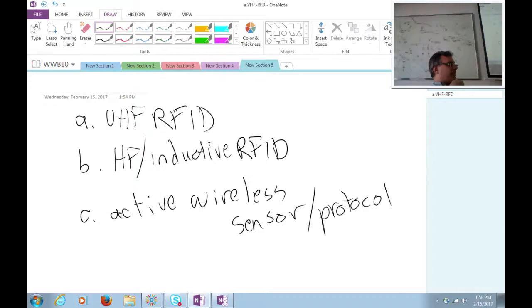I think so too, yeah. In fact, there are casino chip counting technologies based on this. You need to get through a table, which hopefully is not metal. You need to be able to read close in, so using something that's magnetic field based. Magnetic fields aren't disturbed by dielectric materials. It's obviously a short range technology, and it needs to be very reliable with a tight bubble of coverage, right? You don't want to count the chips on the table next to you. Then B is the way to go.